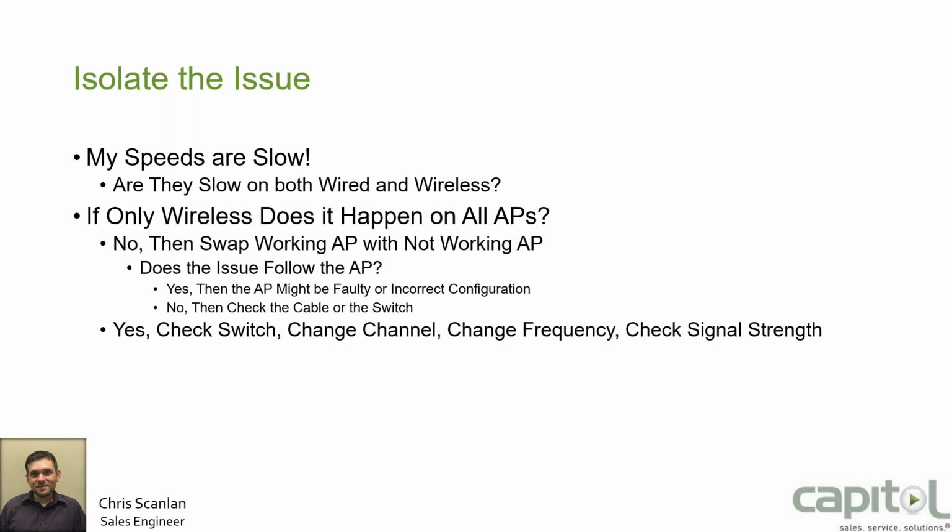Like I said, a customer came in and all of a sudden they put a bunch of mirrors on one wall. Well, a lot of mirrors have a lead backing or metal backing behind that mirror, reflective surfaces. All of a sudden that degrades the wireless signal. So even though the facility had great signal strength throughout when you did the install, the end user may have come back and done stuff to the house to change the artifacting in that facility.